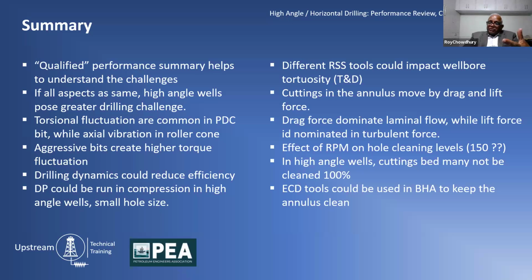This is probably the most difficult situation, I understand, but I have worked in Australia on CBM projects for a few companies, and they tend to avoid it, they don't even use a jar in the coal, and they straight away leave the BHA to come out. They will have the cheapest BHA, and if they can't release it very fast, they will come out of hole. Not a very good answer, I know, but hey, that's a cost.